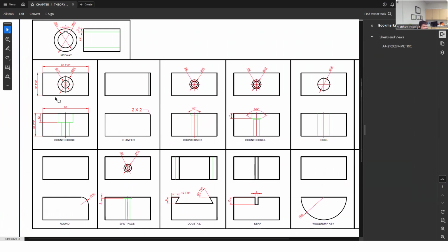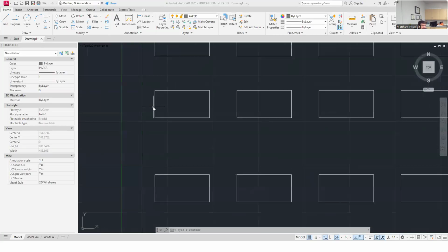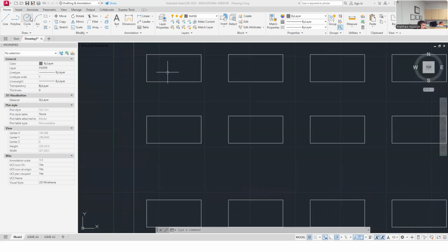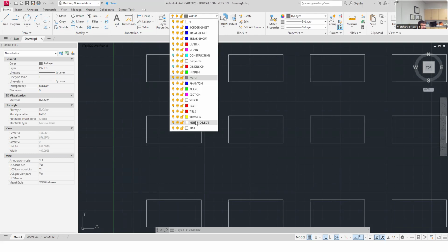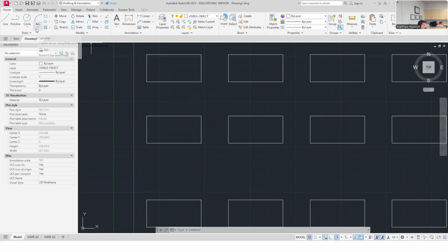But I will start this with the top view, and I'll do these 2 diameters on the geometric center. So I'm going to do a 20 millimeter diameter, and a 10 millimeter. And so let's do that. 2 circles on the upper. Yeah. This one here. These are going to be visible. These are looking top down at a block that has a counter bore. A machinist would have had to put a counter bore into something like this. We can 3D print stuff with a counter bore in it.